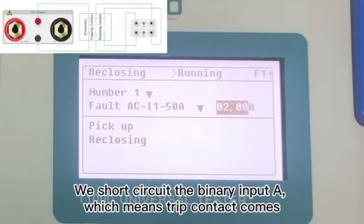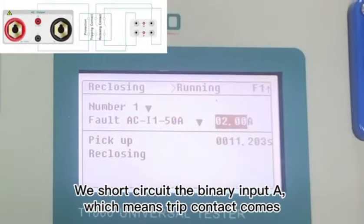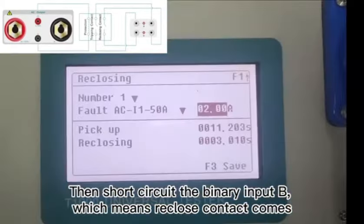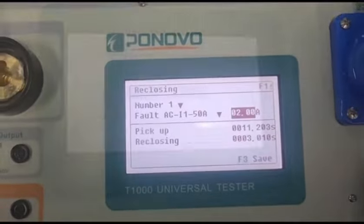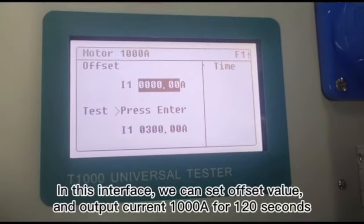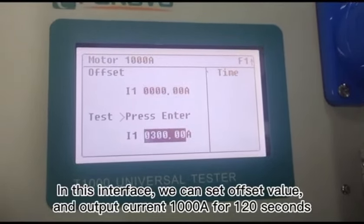We short circuit the binary input A, which means trip contact comes. Then short circuit the binary input B, which means reclose contact comes. There is the pickup time and reclosing time. Next is motor overload test interface. In this interface, we can set offset value, and output current 1000 amperes for 120 seconds.